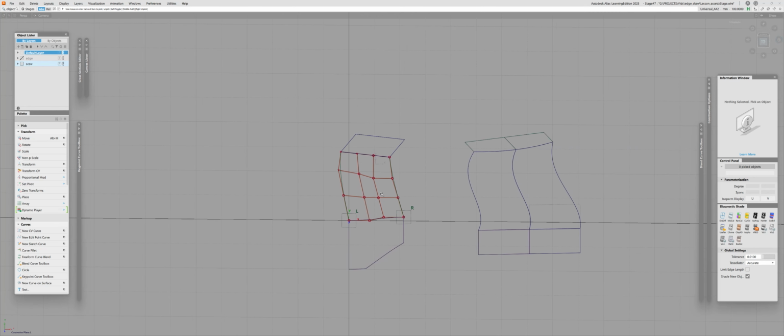Okay, now let's go to the second example, and actually I believe it's pretty clear why edge align is useful, because it creates the proper natural transition between the edges of the surfaces and creates the flow. But the skew doesn't create the flow, or at least it doesn't create a natural flow. Instead, the skewing angle gives you an ability to create your custom flow. A really prominent usage of the skew alignment is when you are rebuilding some parts of a fillet, for example.